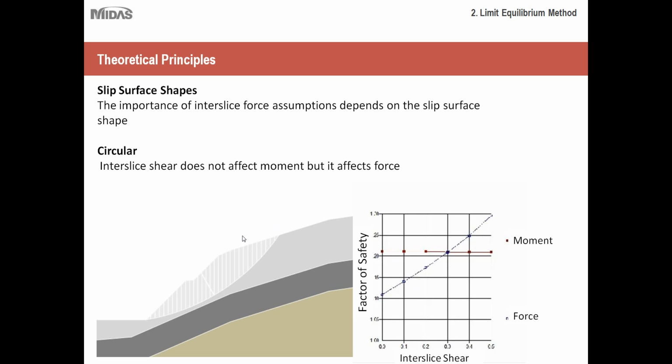So that's another important thing to keep in mind: when you're creating your slip surface or your shape, you need to keep in mind the type of force that you'll be applying to it. Because as you can see, if you're doing a moment type force or rotational type force, it's not really going to be accurately represented here because the factor of safety is not going to change with any increase. Whereas if you're applying any sort of lateral or transverse loading, then this type of model would work well for you because, as you can see, the factor of safety is increasing, as it should.